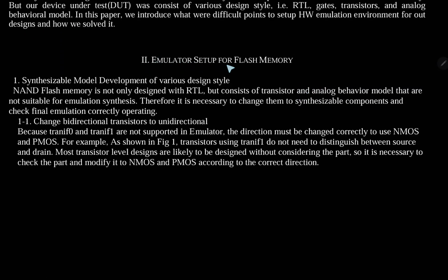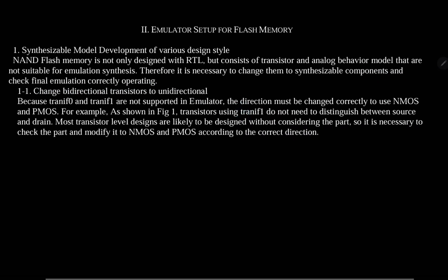2. Emulator setup for flash memory. 1. Synthesizable model development of various design styles. NAND flash memory is not only designed with RTL, but consists of transistor and analog behavior models that are not suitable for emulation synthesis. Therefore, it is necessary to change them to synthesizable components and check that the final emulation operates correctly.